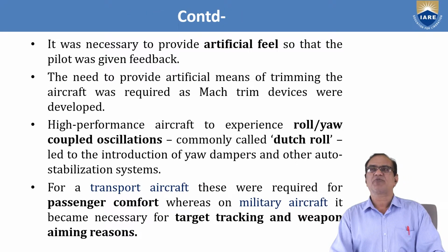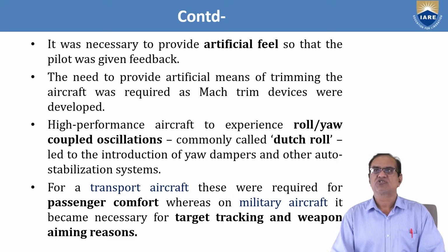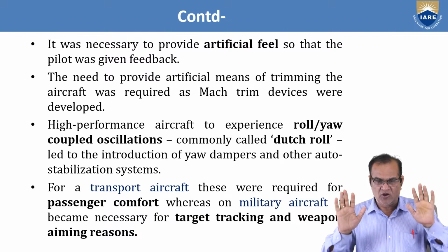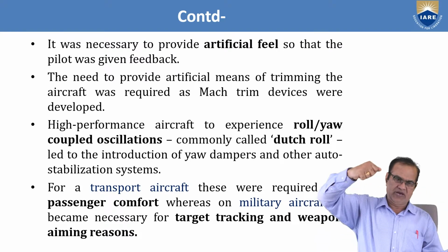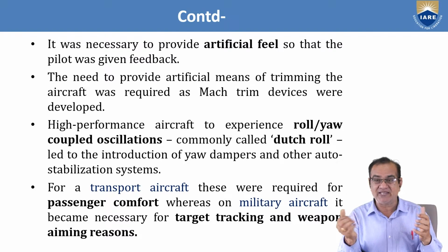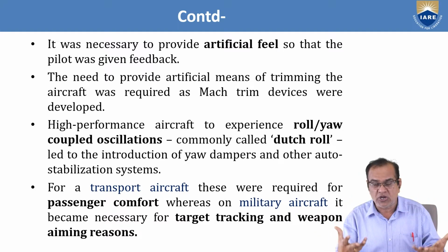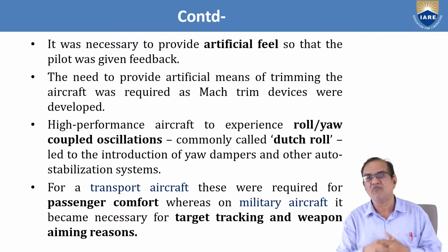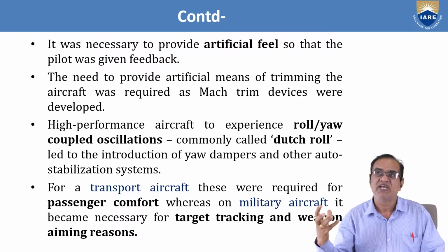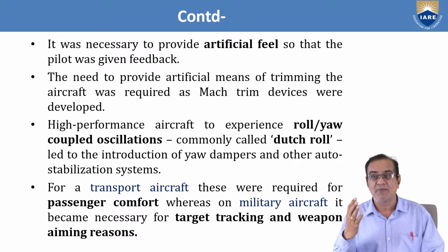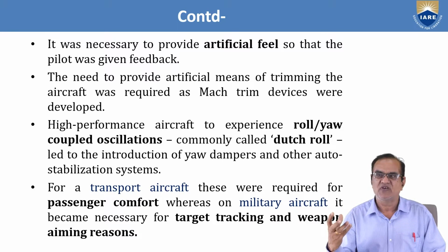It was necessary to provide an artificial feel so that the pilot was given feedback. So it is very much essential that how much pilot is putting the stick, nose down, nose up, rolling left, rolling right. Pilot has to feel in his hand how much he is turning, how much it is nose up, or it is a rudder. He has to feel in his leg how much effort he is putting and how much action is taken by the aircraft. So we need some artificial feel, that pilot should experience how much the feel it is felt.